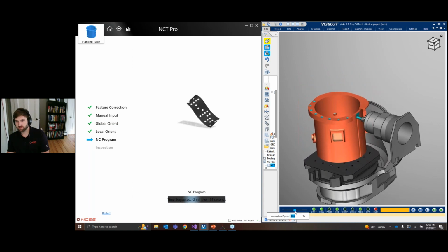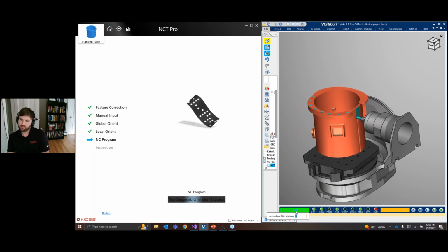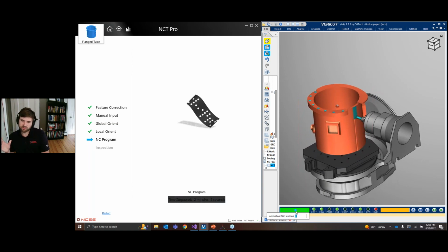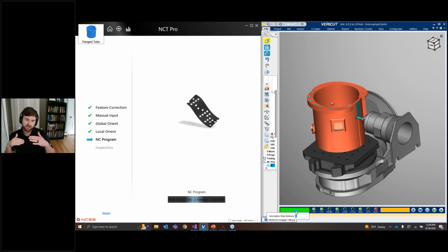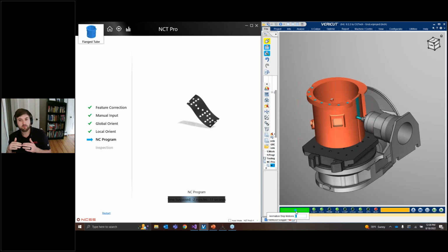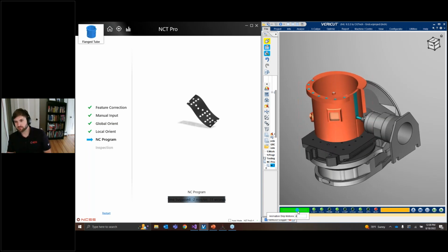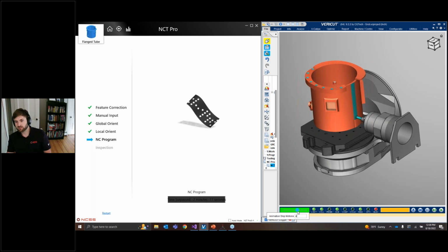Well, speed it up just a little bit. This weld takes a minute. So I'll show you later that this weld's actually been adjusted so that there's a mismatch between the two sides. We're not going to leave any gouge or excess as it would if we'd run it nominally, because we probed up both sides of that weld. Speed up just a little more.